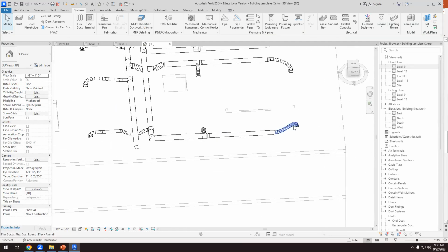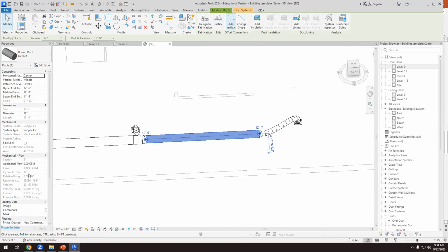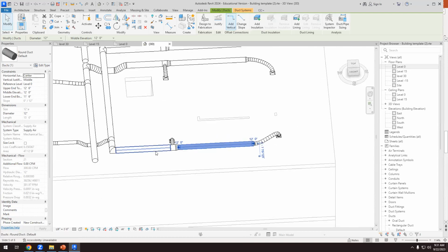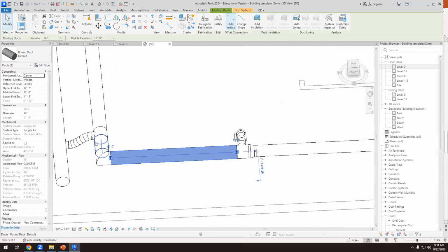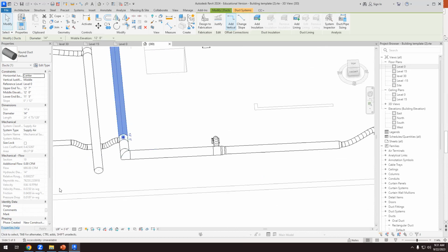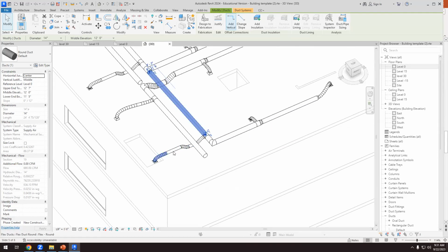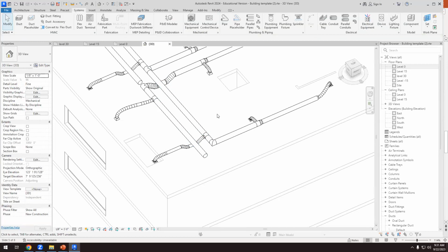So now this is closed. Okay, so we have the first diffuser. This is 300. The first duct, this has to be 300. Then the second duct has to be 600. And now this has to be 600. Good. And this has to be 680. It is 680 because I'm connecting the office space here.